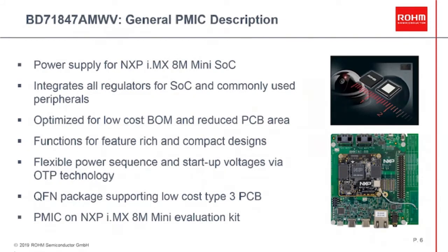Let's have a distance view of this PMIC. As mentioned, all power supplies for the SoC are integrated. And it's not just the ones for the processor. It's also for commonly used peripherals like the DDR memory, flash drives, or SD cards. Additional features are included in the PMIC for compact designs at a very low cost bill of material and smallest PCB requirements, even while supporting low cost PCBs. The PMIC offers OTP technology for power attribute modification and best flexibility.